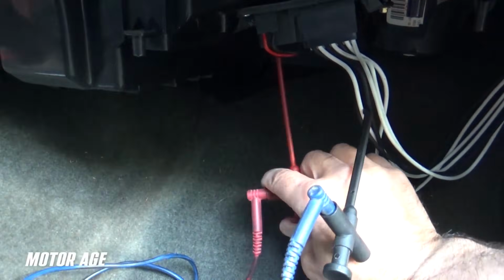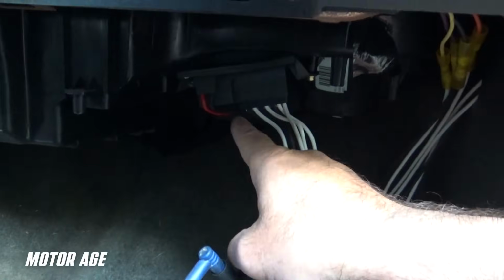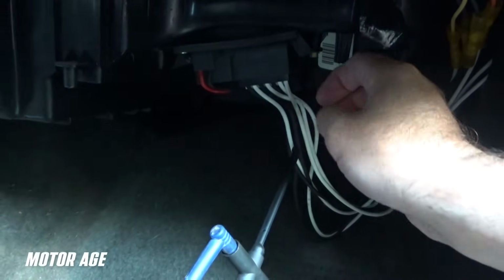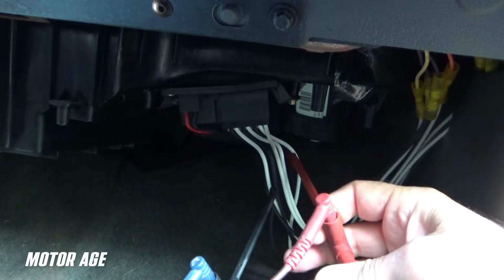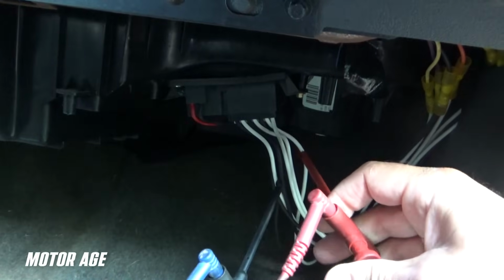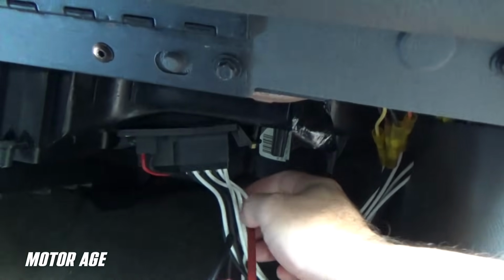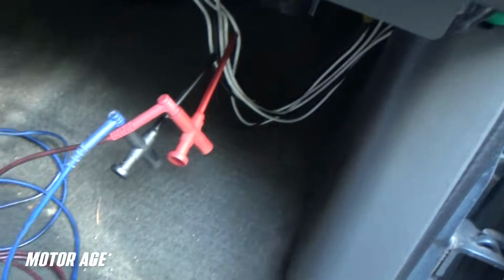So what we're going to do now is move our test lead from the blower motor positive, which was the red wire, up to terminal B of the resistor module, because terminal B is at the resistor module where it should receive voltage from switch position number 1. So we're going to remove our test lead from here, and it reads A, B, C, D, E, F, G from right to left. So this would be terminal B right here. We're going to connect our Pierce probe. I almost always pierce wires, just to ensure I have a good connection to the circuit. We can always repair them later.